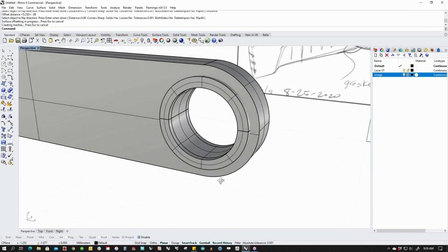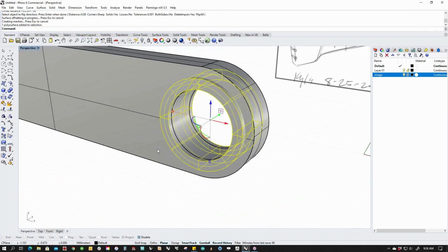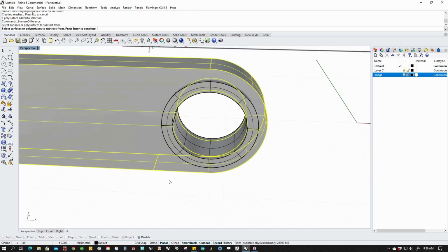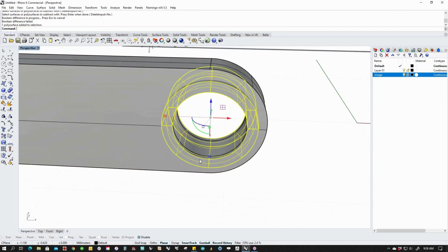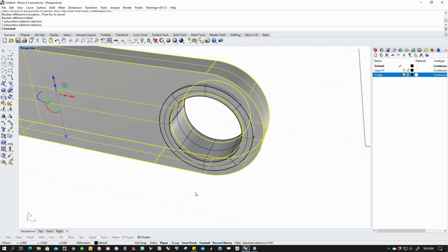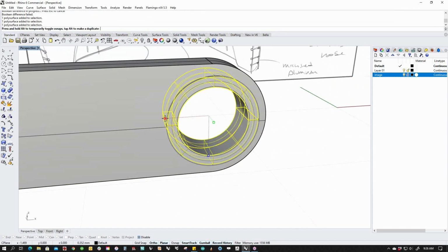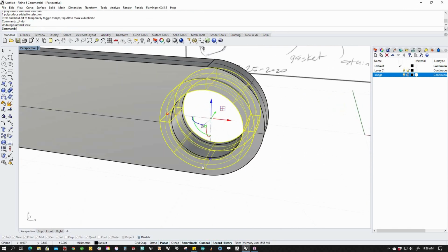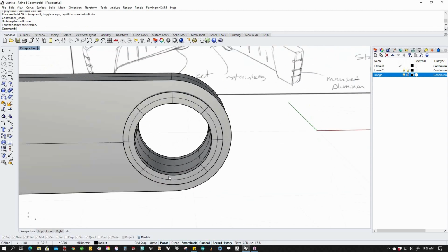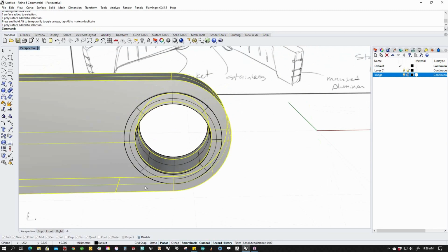That's reasonable, right? If that was some sort of gasket or some sort. So I'm going to Boolean subtract from this using this, and then check and make sure there's nothing left inside of there. It looks like my Boolean failed, so I'm going to just scale this just a tiny hair. See how those were coplanar? See this edge right here is coplanar with that surface. That's not a great Boolean setup, so I'm going to just scale it microscopically